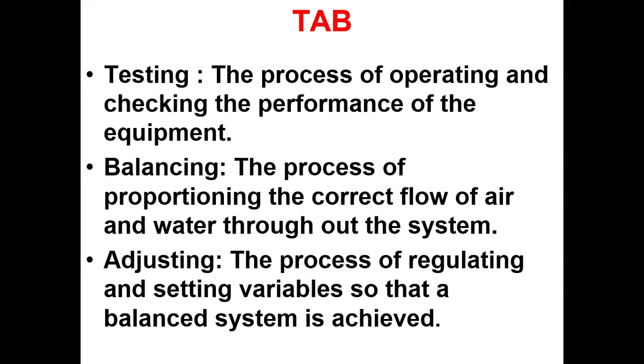That's it. Then, as in the case of water balancing, for each and every AHU you have a balancing valve, not a modulating valve. You need to set the balancing valves. According to the capacity, it will allow a certain quantity of water, isn't it? So once you set the entire balancing valves across the entire chiller system, then you run the chiller. Obviously, if there is any pressure imbalance happening, you can take the reading from the respective pressure gauges deployed around each equipment itself. So that's how you balance your water.